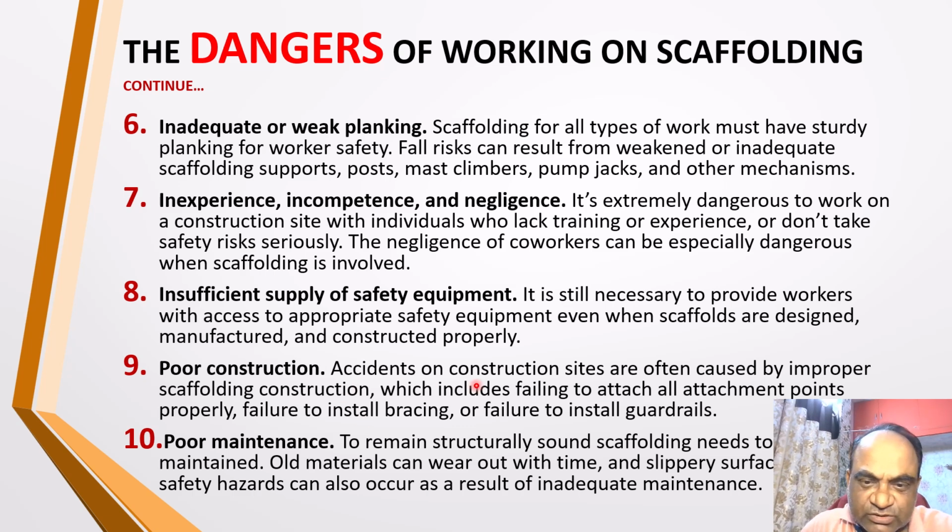Accidents on construction sites are often caused by improper scaffolding construction, which includes failing to attach all the attachment points properly, failure to install bracing, or failure to install guardrails. These could be the causes of an unsafe situation.